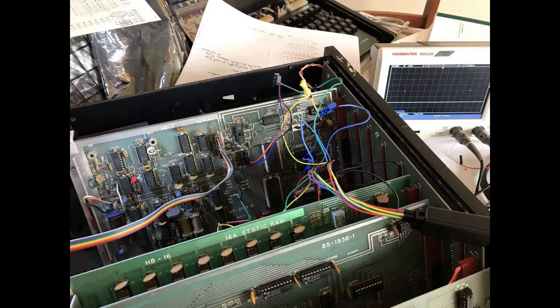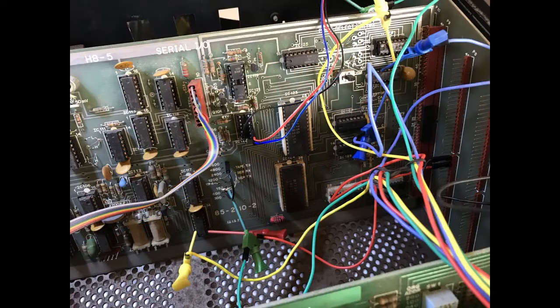So in order to make sure that decoding was all working correctly, we needed to use more than just an oscilloscope where you can see 1 or 2 channels, and I used a small logic analyzer, which I have, a little 8-channel USB one that goes onto the laptop and lets you gather quite a bit of data, and is usually quite useful in these sort of environments. The difficulty was it didn't really give enough ability to select specific addresses and granularity, so I had to finally break out the not that long ago acquired HP analyzer.